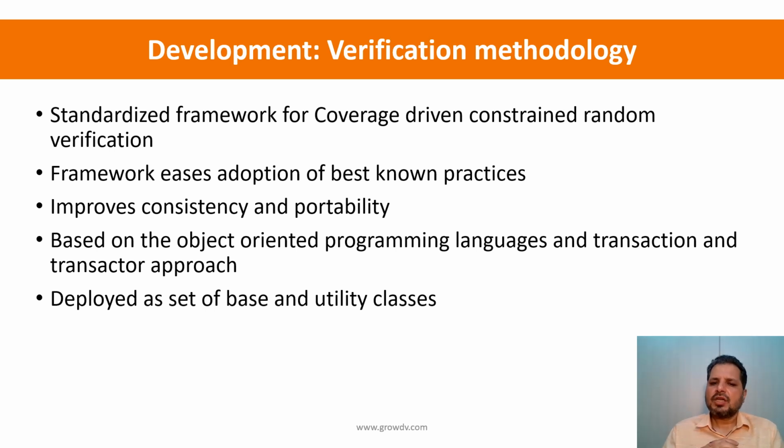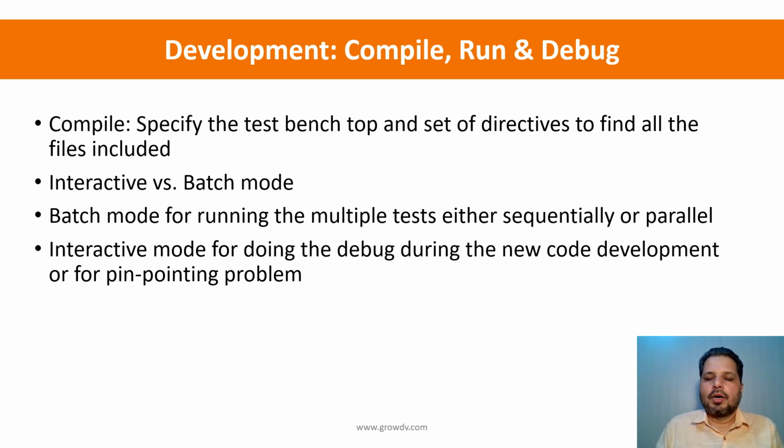And so we use this verification methodology and the high level verification languages to realize the entire test bench that we had shown, following the task list that was created as a part of the planning phase. That's the main activity that is done as a part of the development. So after you have developed a test bench wherein you have the test bench top where you have connected the DUT and you have connected all your test bench components together, and you have written a few early tests, the next step is that you want to start to compile, run and debug the test.